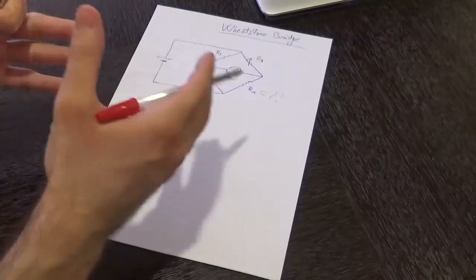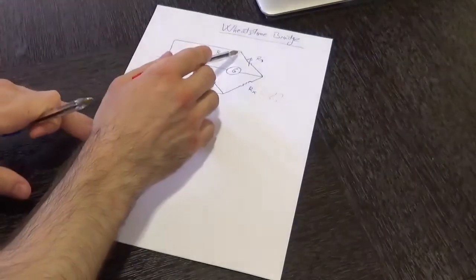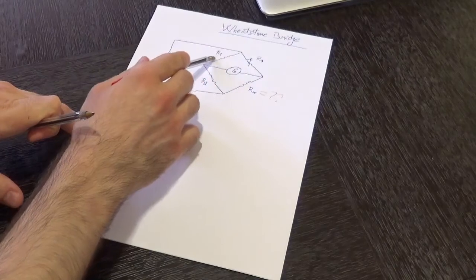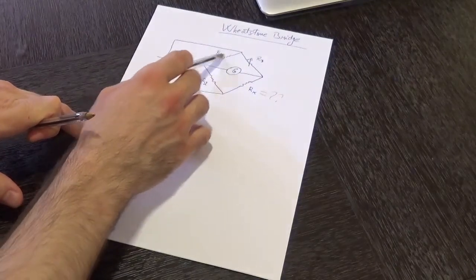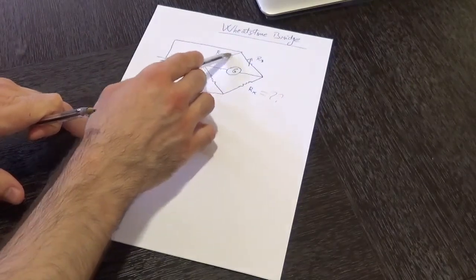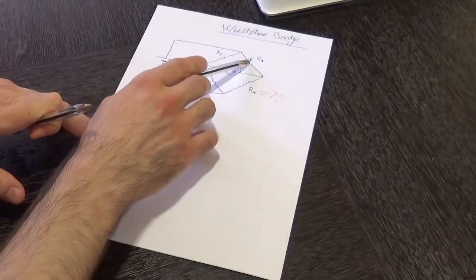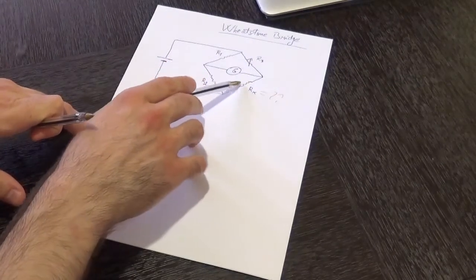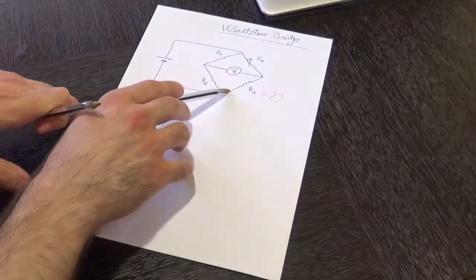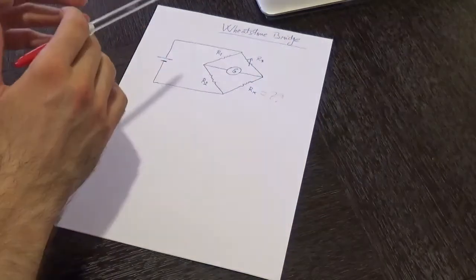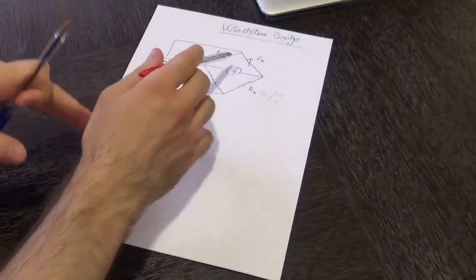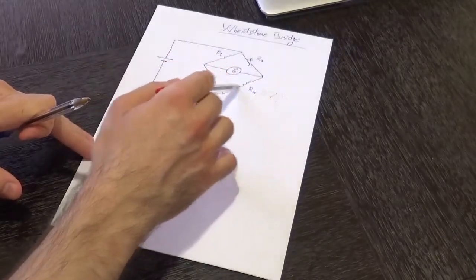So what are these two parts of the bridge circuit? That part over here, which consists of the resistor R1 and the resistor R2, is the first part of that bridge circuit, and the other part, which consists of the variable resistor and of Rx, is the second part of that bridge circuit. So the Wheatstone bridge consists of balancing out these two parallel parts over here.